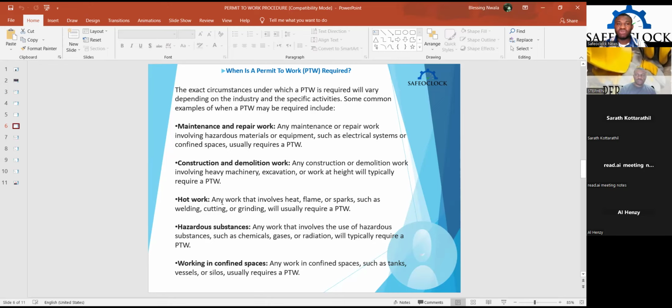You should be able to know if the hazard has been properly identified. You should verify that the permit was properly filled, the date is accurate, the risk is identified, and the control measures are sufficient.